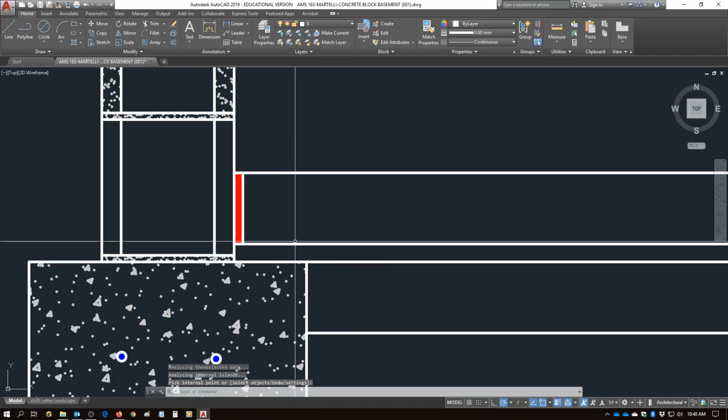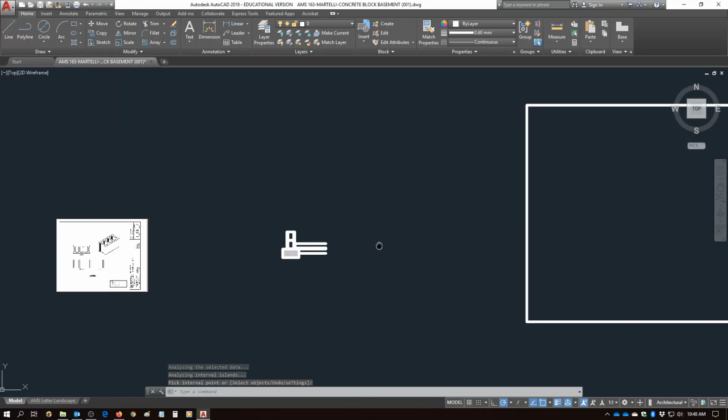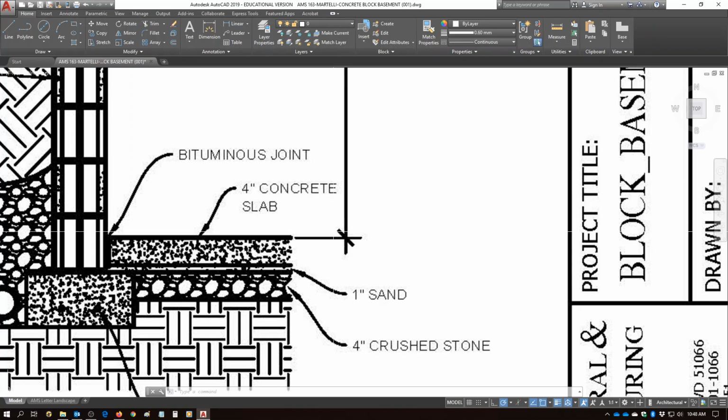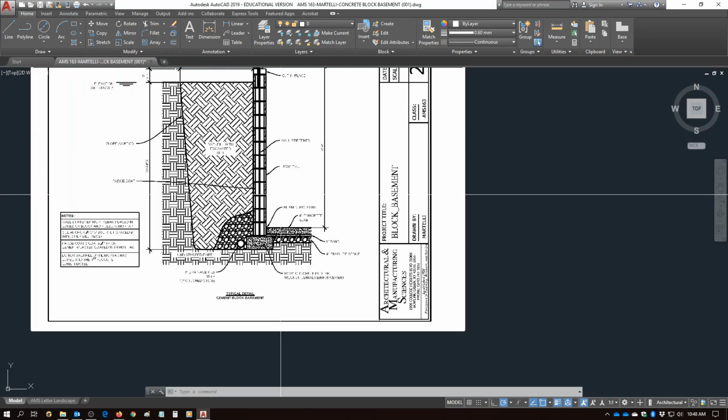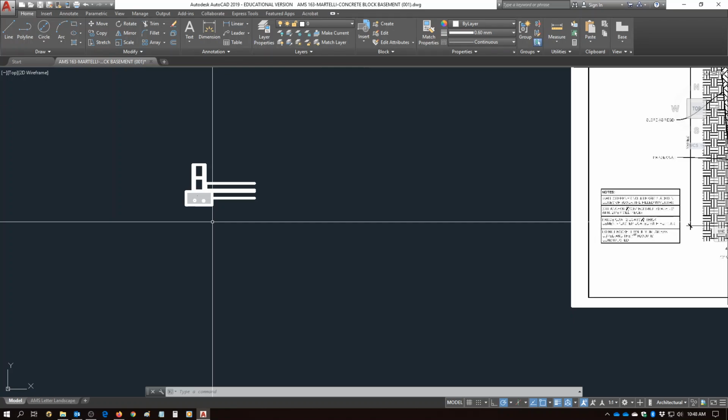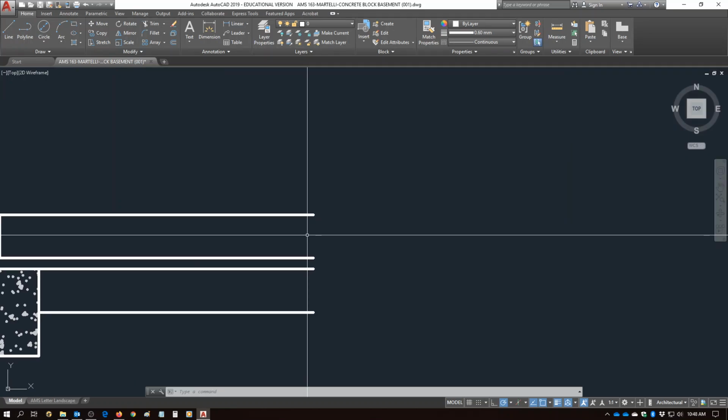Now we're going to draw another very special line. You see, this construction actually technically goes on and on, but we're trying to zoom into the assembly of it. So the line that we're going to draw is called a continuous break line. And the typewritten command to type in is BREAKLINE, break line. Kind of like your car, but spelled differently. So I type in break line.